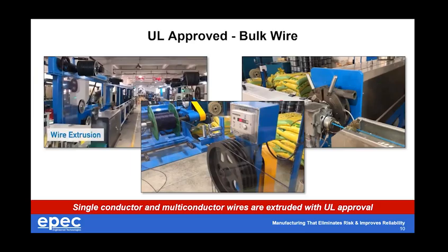Once the raw wire is extruded, sometimes a shield or overbraid is added, and then sometimes additional legs are spun with the wire, yielding the finished either single conductor or multi-conductor cable. The final step of the process here involves part marking to comply with UL. In order to fully comply with all UL requirements, the UL spec, voltage, and temperature are printed along the circumference of the wire jacket, and then it's spooled into various different sizes and drums depending on the application and where this is being used.